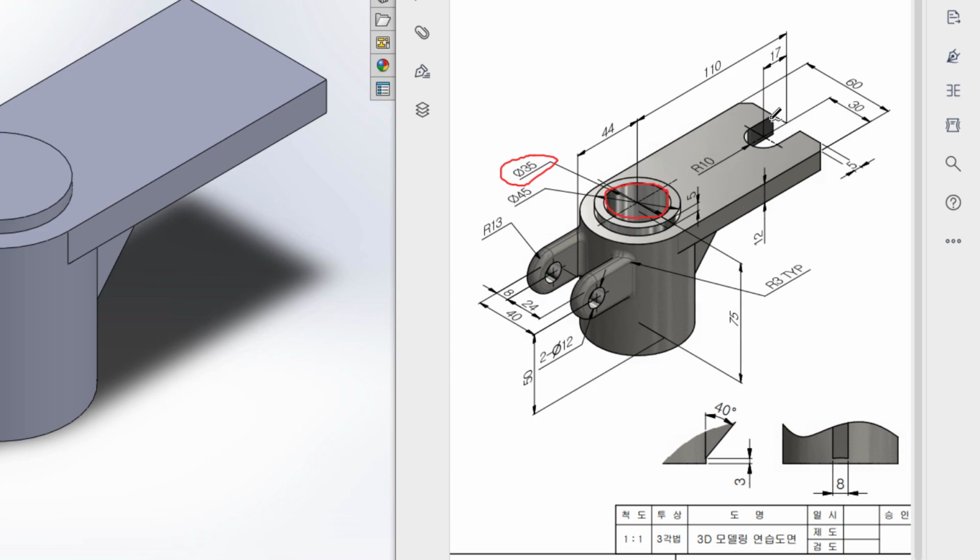Then we can see we have another cut here, and for drawing this cut, first of all, from this midpoint I'll draw a center line, and this center line will be a dimension of 17 unit. Then we can see as the radius is 10 unit here, so I'll draw an offset of 10 unit here and another offset of 10 unit here. After that, I will draw a semicircle on this of 10 radius. Then I will close the shape. Then I will also extrude cut this portion.